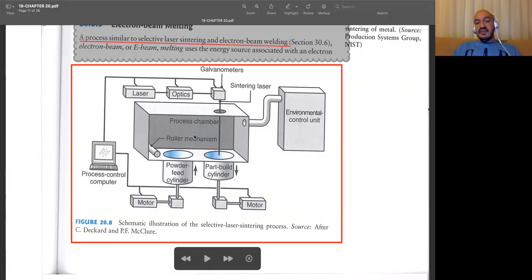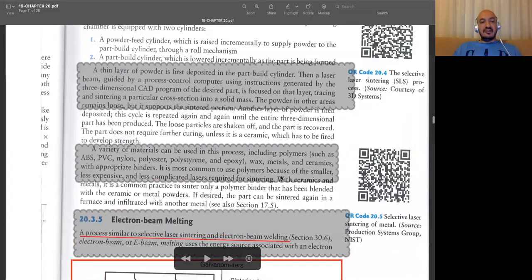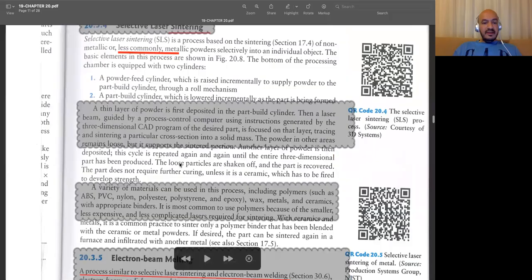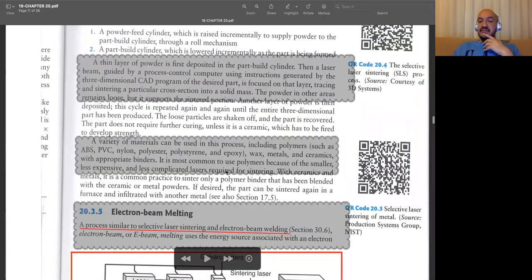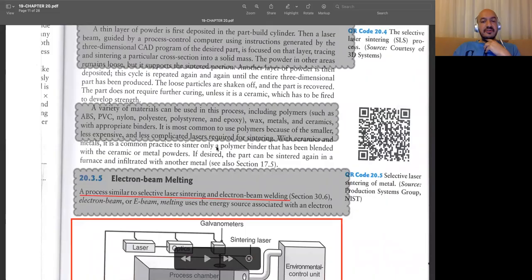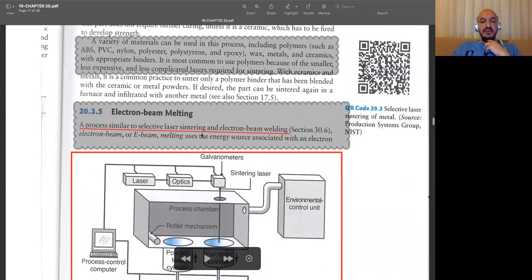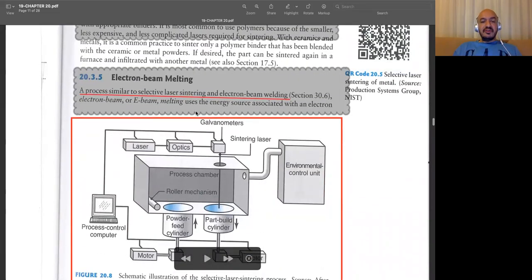And in order to decrease laser power, we may also have some extra heaters inside so that the powders may be increased to some temperature first, and then with the help of the laser, their temperature may be improved a little bit more. So that by using less laser power, we can do the same process. I will again show you an example of this process in the lecture, so I'm not going to discuss it anymore.